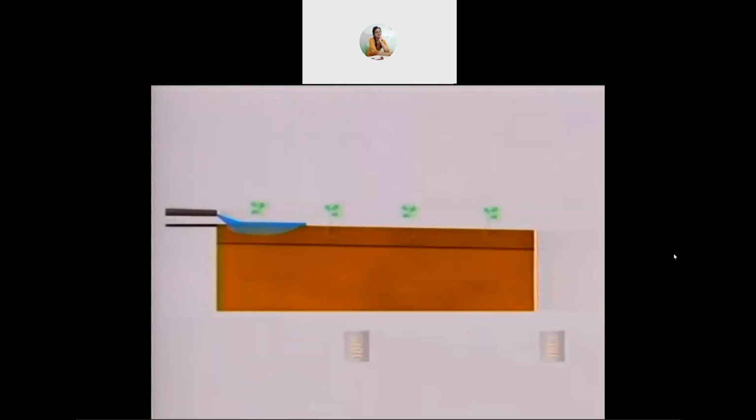The difference in how much water enters the field at different locations along the row is called uniformity. Field A has a high uniformity. Field B has a low uniformity. This irrigation has high uniformity, but too much water was applied, resulting in water lost to deep percolation. This field is just right. Unfortunately, it's also impossible.